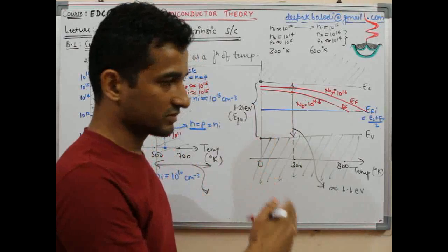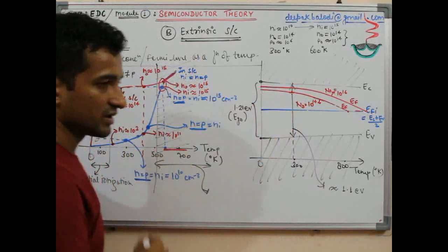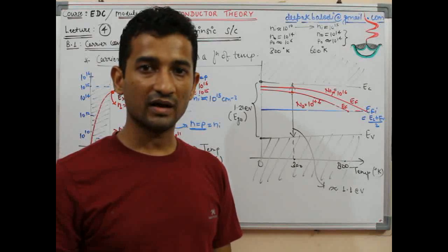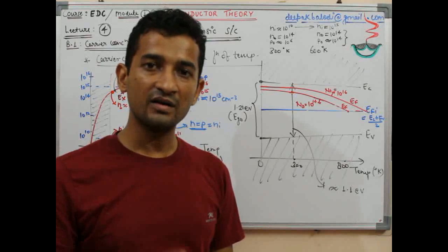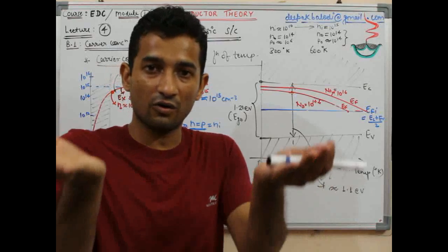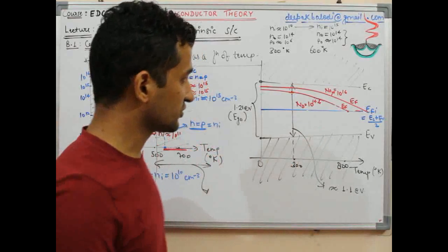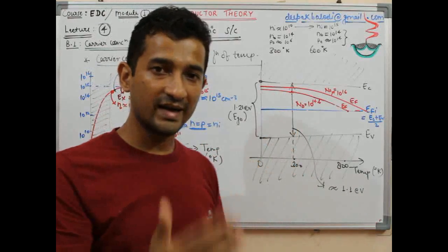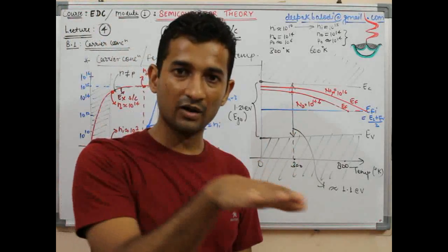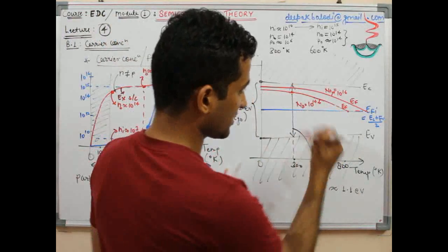So I am saying that this is the Fermi level, this much below EC. But as we are increasing the temperature and entering this range, the intrinsic carrier concentration is shooting up. Therefore, an extrinsic semiconductor is indistinguishable from the intrinsic, because the number of minority carriers has increased too much. So in order to indicate that extrinsic has become intrinsic, the Fermi level should again come back to the intrinsic Fermi level. So it is coming and lining up with this.